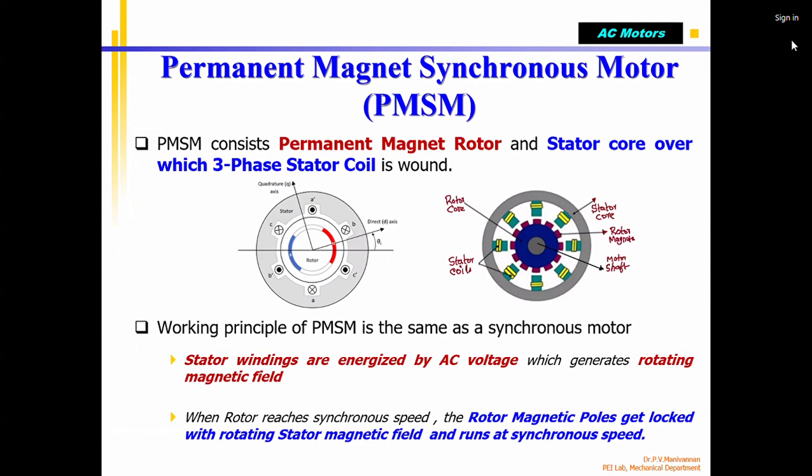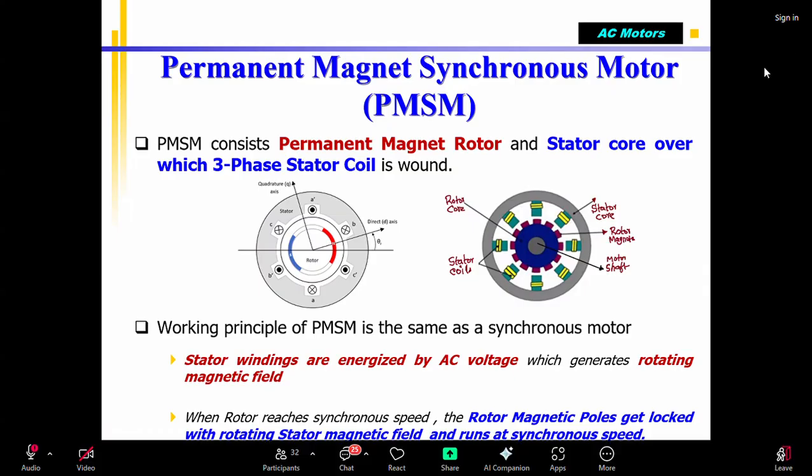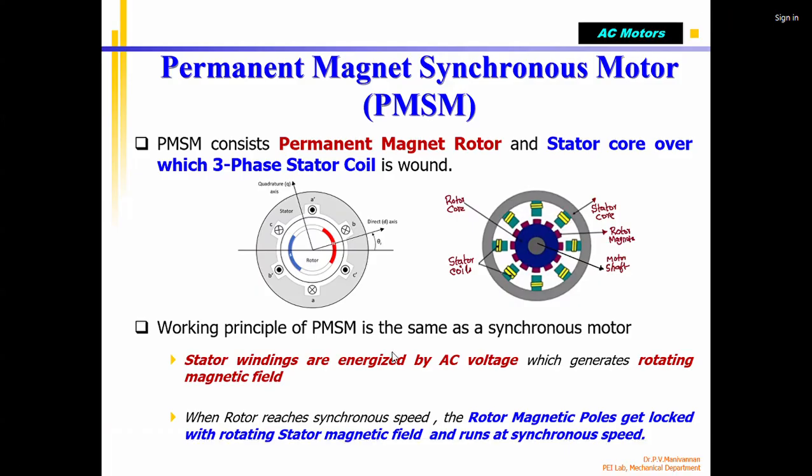These additional coils, called starting coils, are fixed on the surface of the rotor, and they will be energized. That will generate a magnetic field, and that will make the rotor get aligned, get magnetic lock. After that, that power can be stopped, correct? You don't need an external motor. Instead, the starting coil voltage can be stopped, and then the synchronous motor will work.